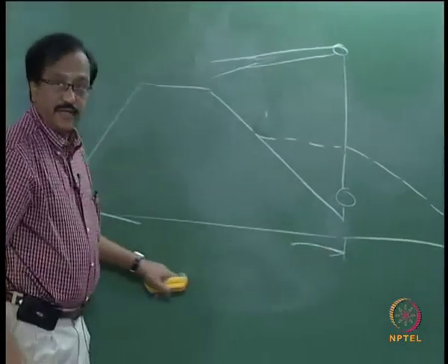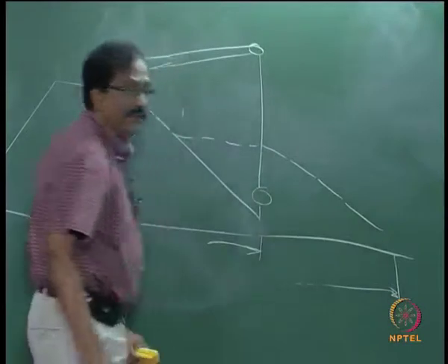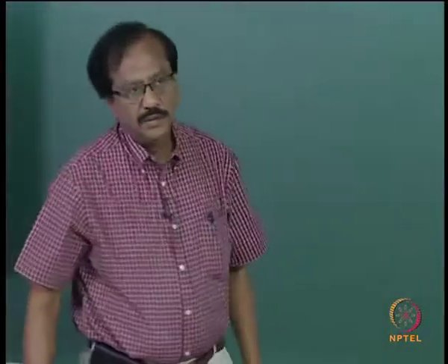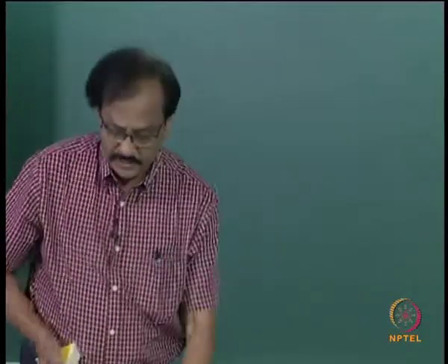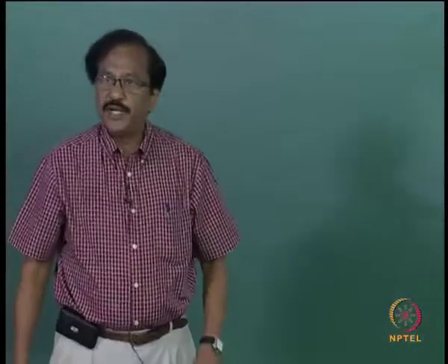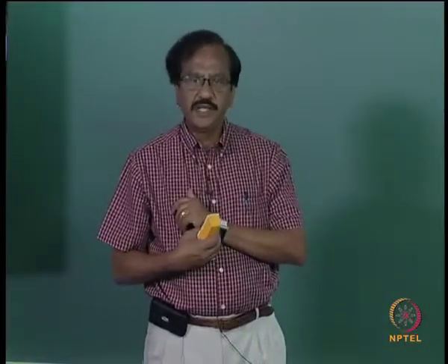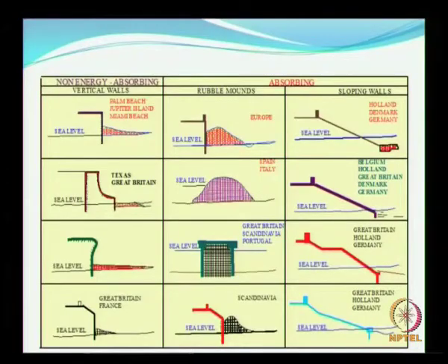This was the original width, but now, because of the berm, you have the increased width. So, these are some of the demerits, but there are merits which are more towards the stability of the seawall. They have claimed from practical experience that bermed type seawalls or bermed breakwaters are more stable.